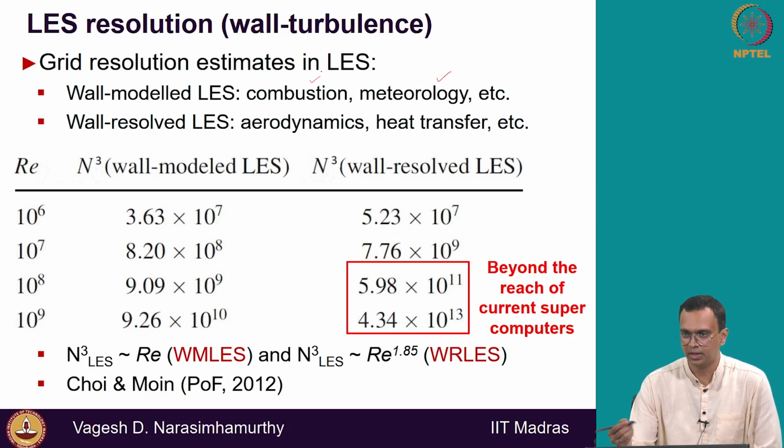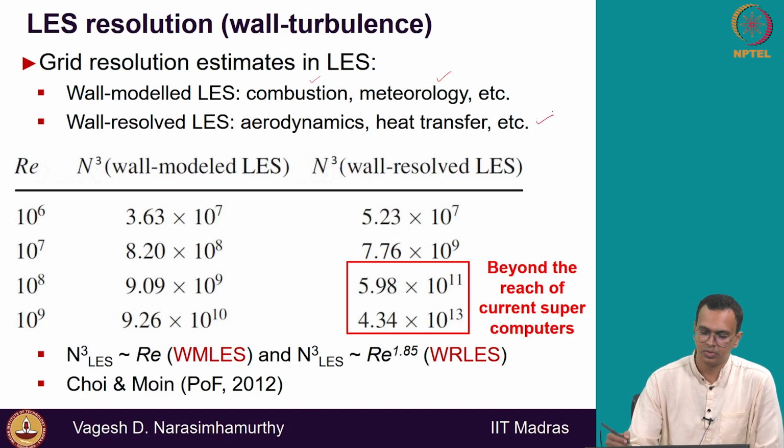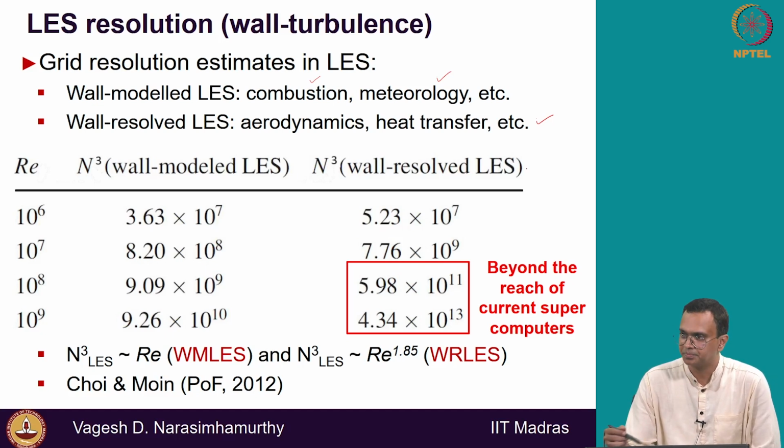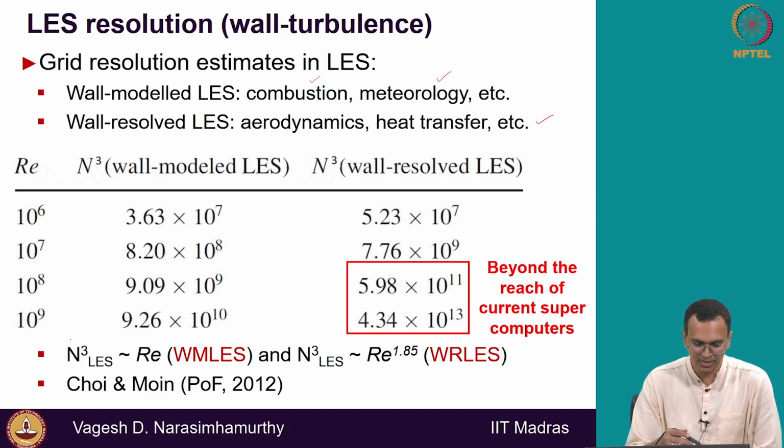But if you are doing aerodynamics, then you need to compute drag, then obviously you need to resolve up to the wall, also heat transfer on your surface. So those kind of problems you have to do wall resolved LES, and wall resolved LES becomes very complicated, very expensive. Okay, and that you can see here, this is just an estimate, this is not telling that we have computed all these flows. This is just an estimate given because we have the formulas to estimate here.